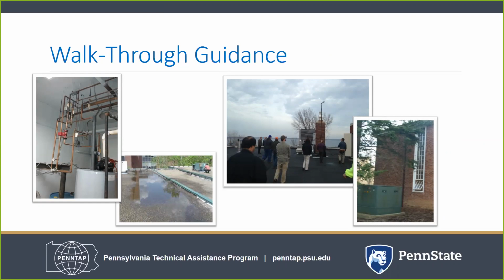You want to investigate during both the heating season and the cooling season. See if everything is operating properly during both seasons. And you want to log all the information and observations during the walkthrough. This will help you capture opportunities and ultimately calculate potential energy savings. There are many areas to investigate during the walkthrough. Look at your lighting, the building envelope, all parts of the HVAC system, your hot water systems, and air distribution.